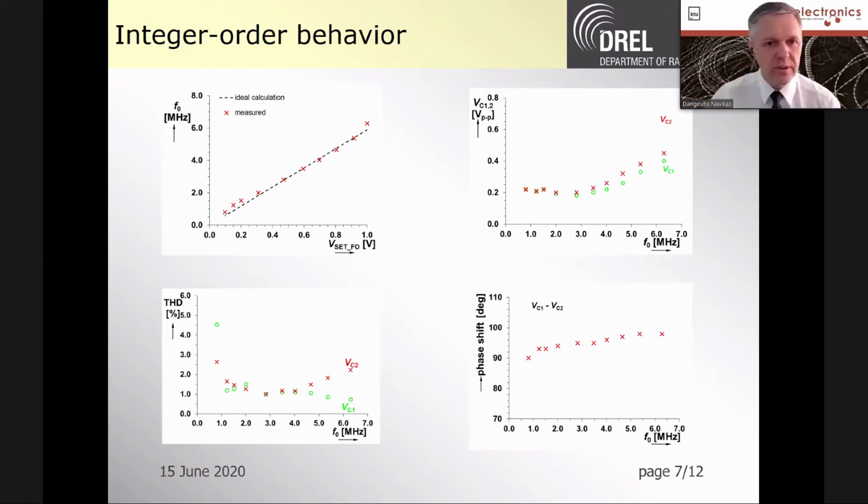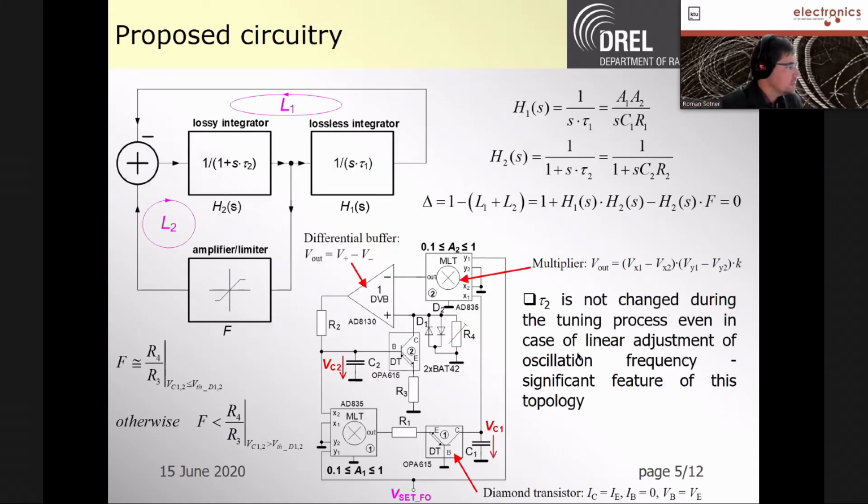Okay, thanks. Could you point out some weaknesses of your solution? Yes, as I discussed, the weakness is the frequency limitation of the devices, because it would be beneficial working with some kilohertz, tens of kilohertz bandwidth, but above, I think, 10 megahertz, there are issues with the frequency bandwidth limitation of active devices.